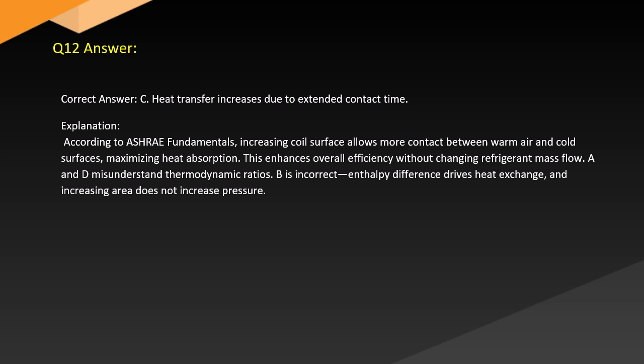Answer. Correct answer: C. Heat transfer increases due to extended contact time. Explanation: According to ASHRAE fundamentals, increasing coil surface allows more contact between warm air and cold surfaces, maximizing heat absorption. This enhances overall efficiency without changing refrigerant mass flow. D misunderstands thermodynamic ratios. B is incorrect. Enthalpy difference drives heat exchange, and increasing area does not increase pressure.